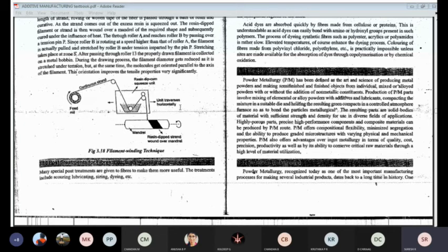The main advantage this process offers over metal forming technologies such as forging and metal casting is shape complexity. We are able to get better shape complexity, and near net shape with dimensional control. Almost the net shape of the product can be achieved in this case. That's why powder metallurgy has been quite famous in the present scenario.